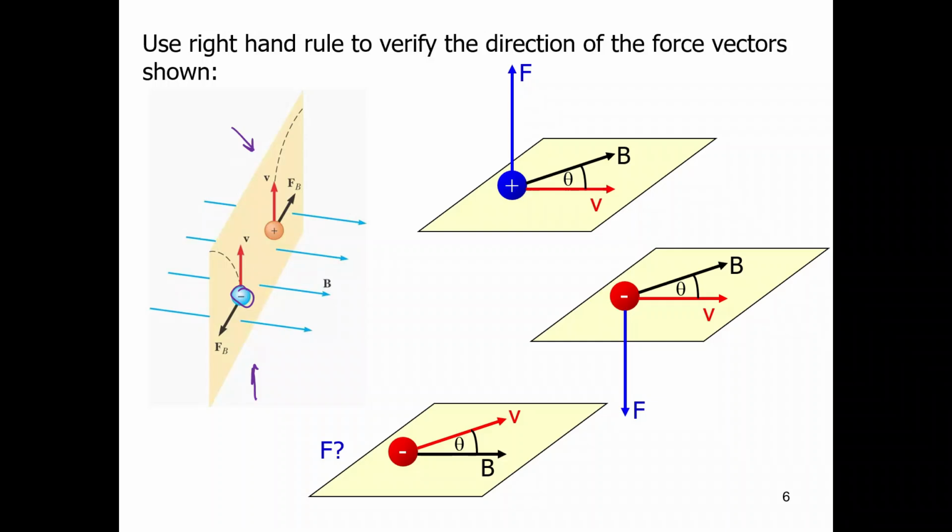So this one is kind of showing your Z-axis is here. I hate forced perspectives. Your Y-axis is here, and then your X-axis. That's positive X, positive Y, positive Z is how this is showing it. So Z is like in and out of the page. X is left and right. Y is top of the page and the bottom of the page. And Z is in and out of the page. That can kind of help in these perspectives.